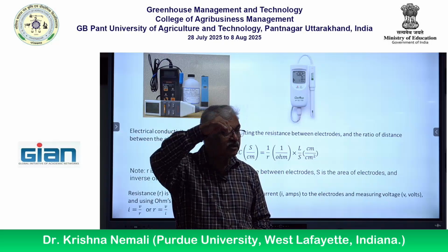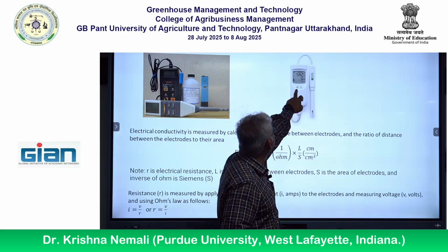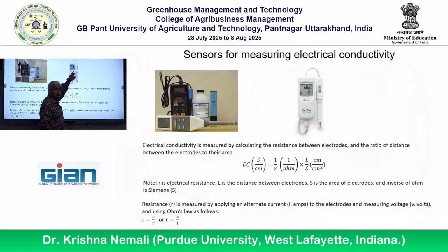There are some buttons on it, or in terms of electrical things, you can actually change the mode to calibration and press some of the buttons and change the numbers. You can type in some numbers, increase or decrease it, or you can adjust it with a screwdriver in older ones. But you have to calibrate.